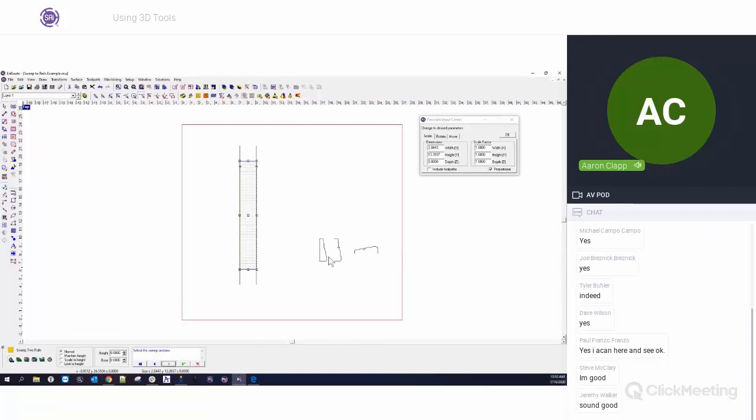So what I do is, if you have a shape like this, you can just simply explode the drawing, delete the lines in between here so that you have a line like this, and then just remerge it together. So it's that easy. I'm going to click it once, and you'll notice that up here we get a green line. That means that we're starting here, and we're going to sweep it down.